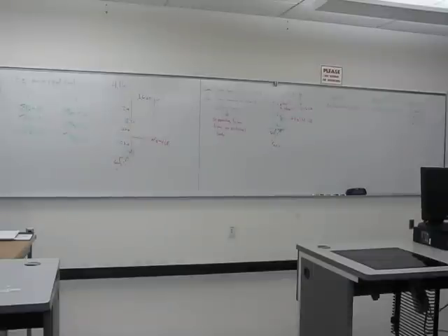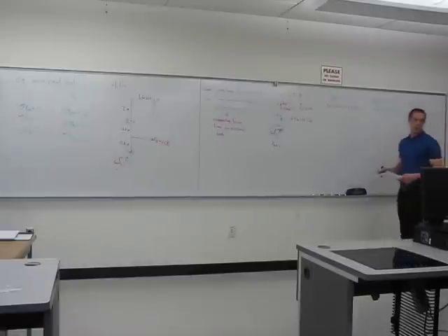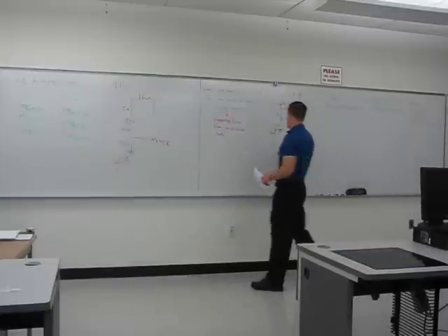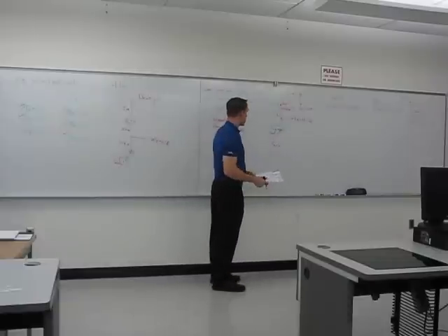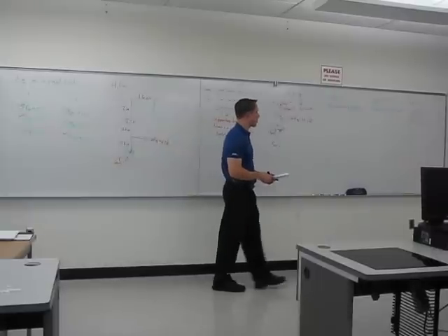So if you plug the numbers in for FB and FD, we don't need sine 60. FA sine of 60? But it's going to be 0, a times 0. Yeah, because that line of action goes right up through the point C. So you could put FA sine of 60 times 0, but there's no need because that's going to drop out of the equation anyways.